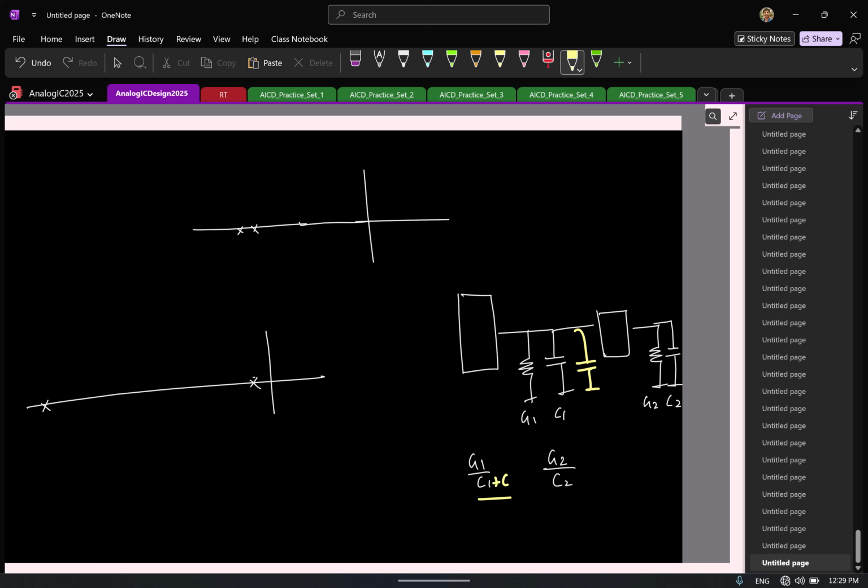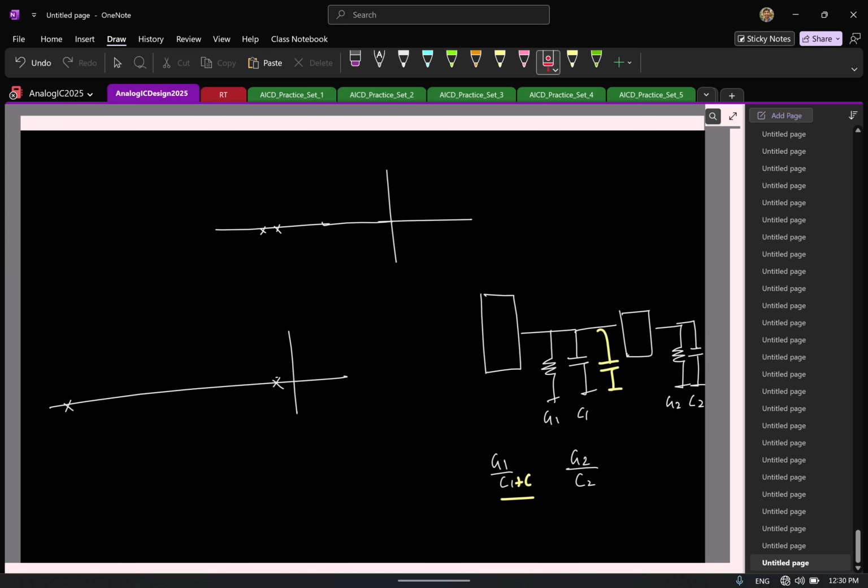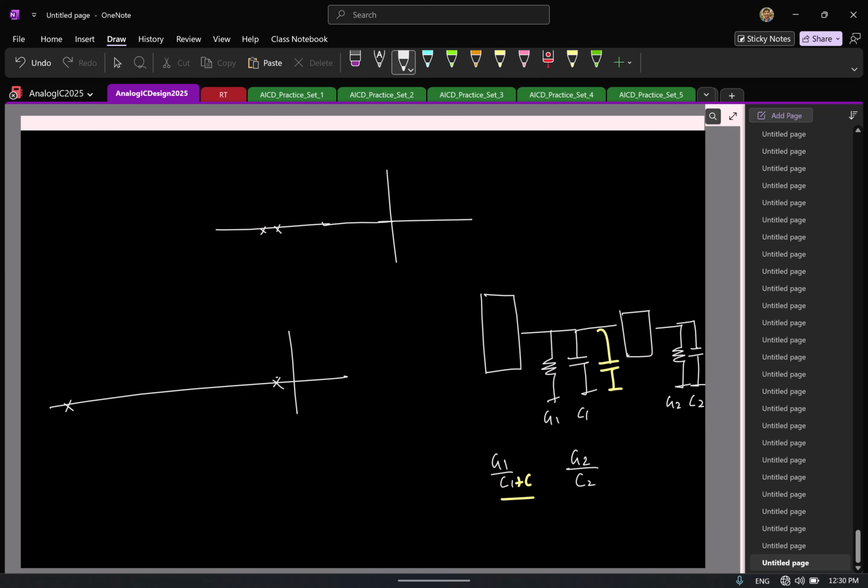Right? I mean, through the Miller effect we put a capacitor here, so the apparent capacitance looks bigger, but instead you can put that big capacitor directly here also. But if you do that, only one pole moves to a low frequency, the other pole remains at the same location, right? So that is a drawback. So sometimes this is also done, and this is called dominant pole compensation. Again, the notion is the same.